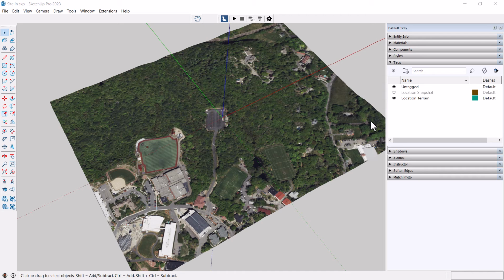Now, I would be doing you a disservice if I didn't show you some other ways of generating site geometry besides picking points. First of all, professionally, you might have site surveys where they have point clouds, individual points where they have taken elevation readings, and you can actually add those point clouds into your Revit file and create a Toposolid from that.